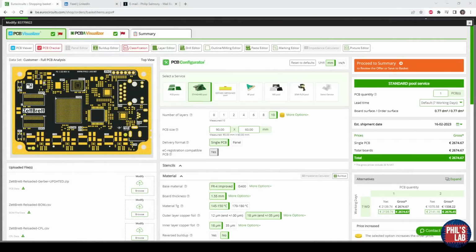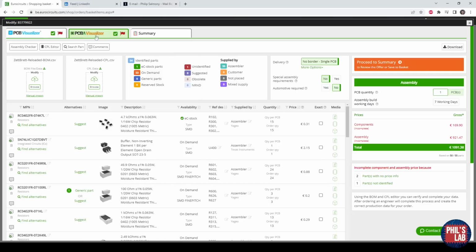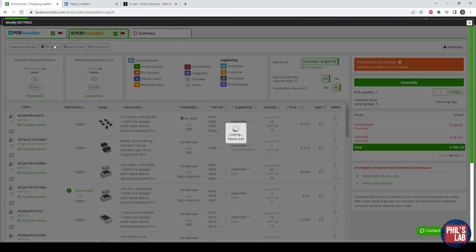This video is in no way associated with or sponsored by Eurocircuits, but I'd like to show you a very useful tool that I pretty much use for every design before I send my manufacturing data or assembly data to my manufacturer of choice. Eurocircuits has a really nice online visualizer and tool for checking footprints and making sure there aren't any assembly problems just before you submit the files to be manufactured. Not only is this good to visualize, for example, the PCB and the Gerber files, but also, as I said, for footprint checking. Go to Eurocircuits, the PCBA visualizer, and then go to the CPL editor.